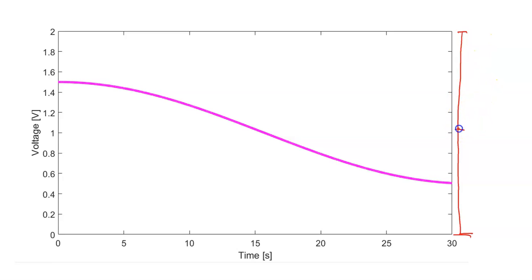So our first bit would cut it in half, and then our second bit would cut those in half, and then our third bit would cut those in half again. So you have a 3-bit converter, that's 2 to the 3 number of bins, so that's 2, 4, 8.